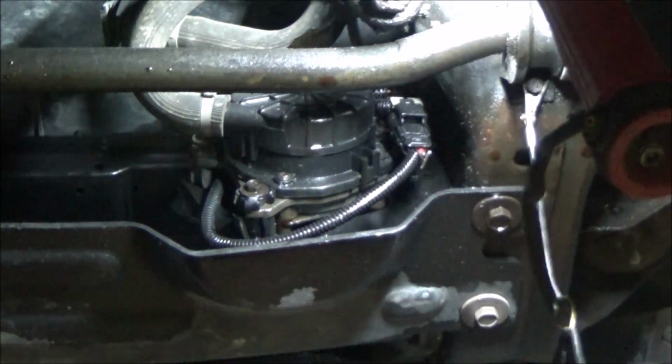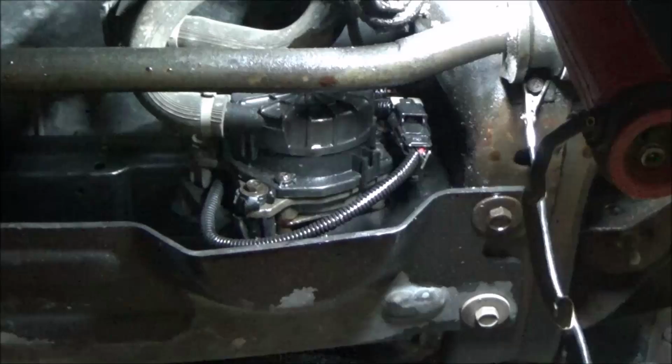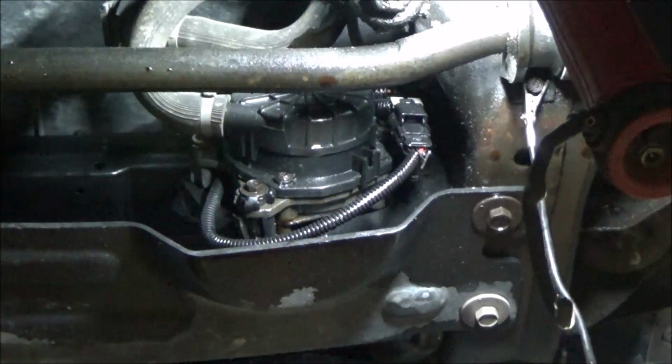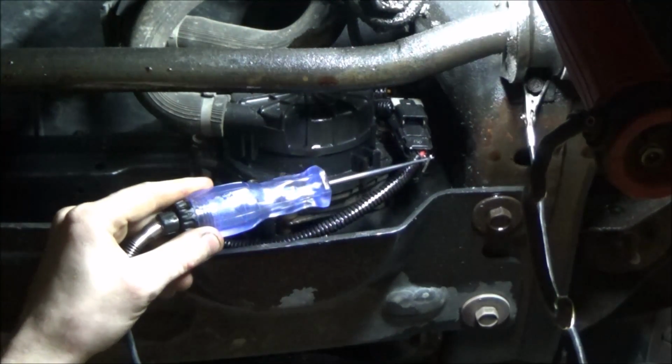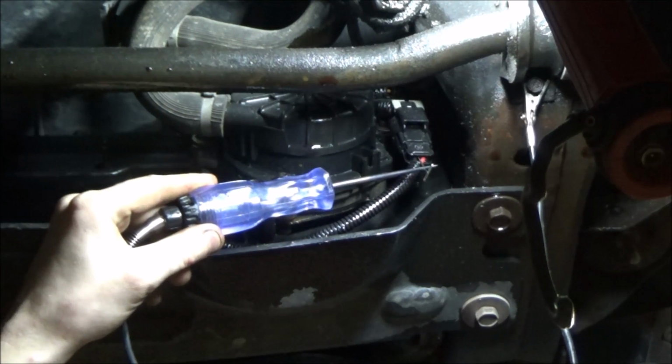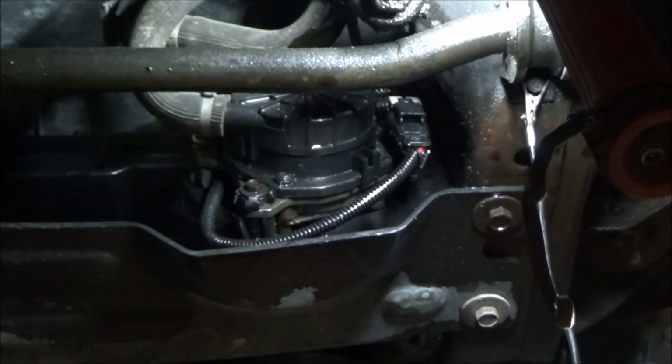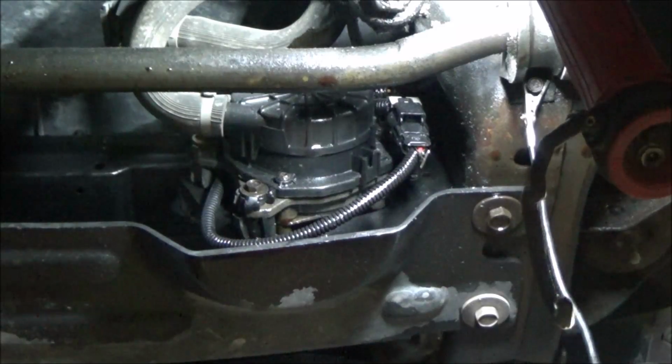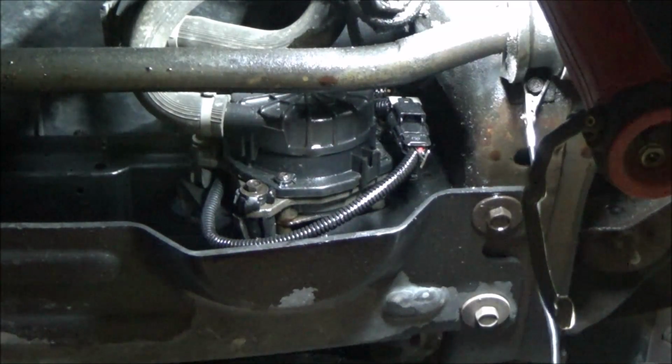So we still have our air pump on, we still have voltage on this red wire. I'm now just going to check this ground location. I'm just touching my test light to this black wire, and we can see it does not light. So without a doubt, guys, this motor's bad. There's a high likelihood we may be able to get it working again. I really hope so, really just to give you guys confidence in what I'm teaching you.